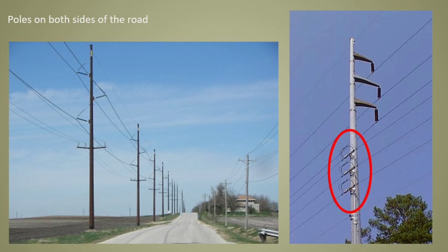So in those instances, when a power company does have high transmission lines on a road, they will often provide distribution power and comms on the other side of the road, just like the photo we have here, where they're providing a place for the communication to attach, but they don't want it on the transmission. At any time that you have an option like this, where you have pole lines on both sides of the road, the pole owner will always push you to one side of the road and not attach on both sides of the road.